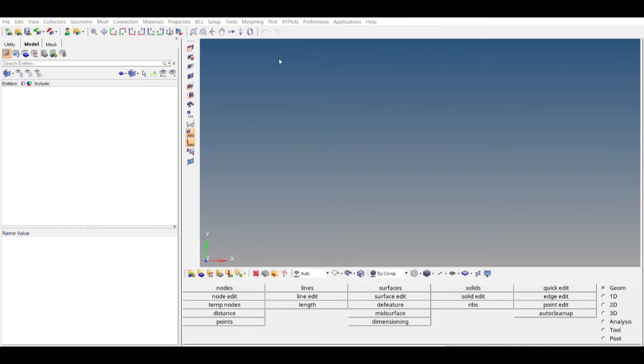So first, since it is a plate deflection, we need to create a plate deflection model. First we'll go to Hypermesh, then we'll go to the Optistruct panel, and we'll start with the creation of the geometry. First we'll go to nodes. As we know, the length of the plate was 100 mm, the width of the plate was 10 mm, and the thickness was around 5 mm.